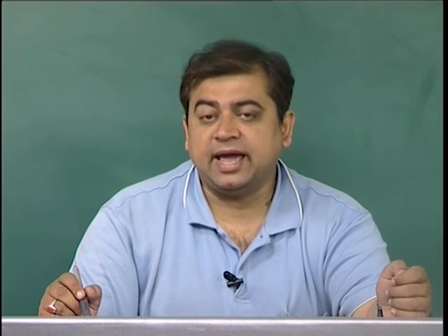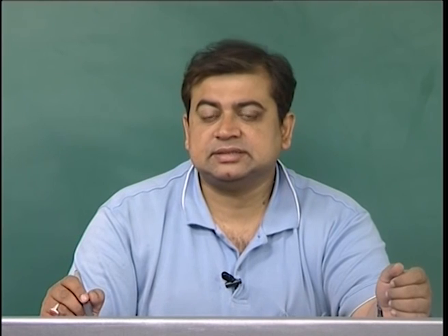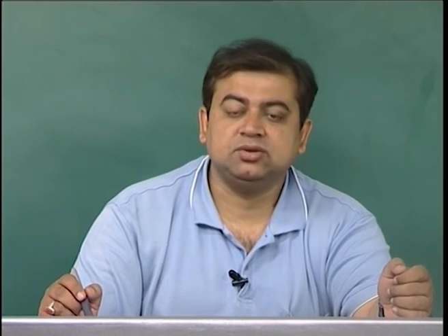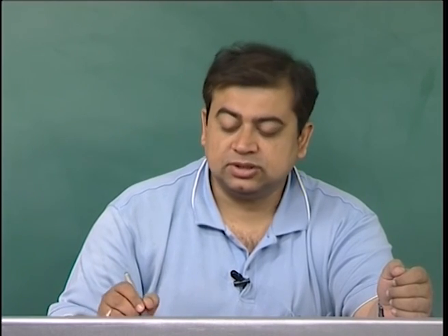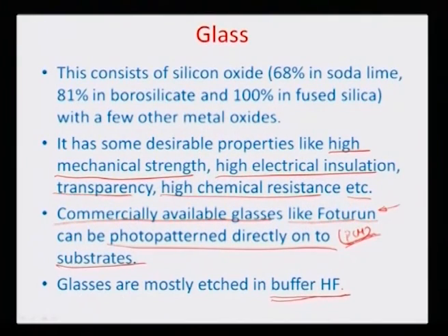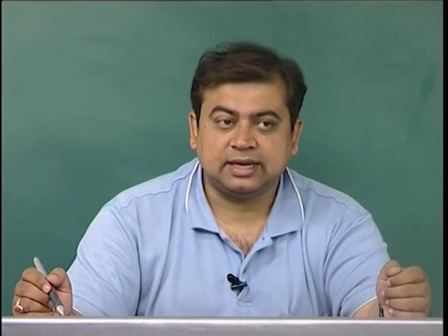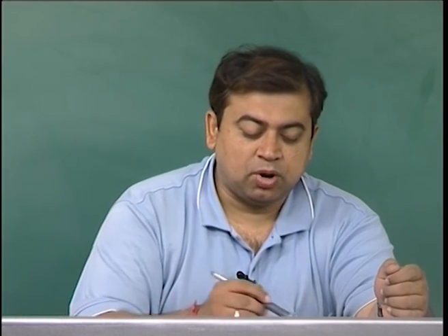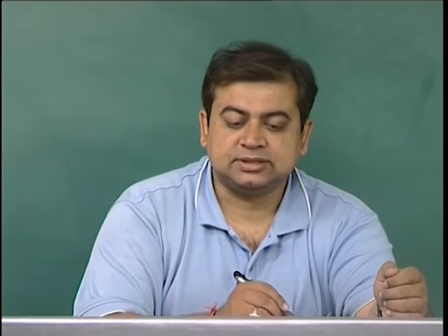So for etching glasses, for creating crevices, cavities, features, structures on the micro scale within such glasses, you normally use buffered HF solution, which is actually a solution of HF along with ammonium hydroxide and water. So that's how glasses are important for the microstructured domains.